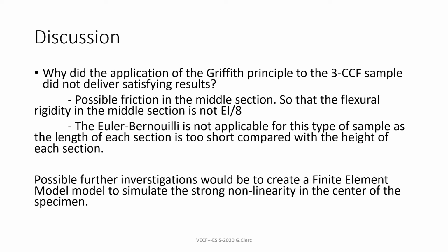For the ENF sample, we use flexural rigidity divided by 8 for the cracked region. But I'm not sure that's the case for the CCF sample, as there is probably a lot of friction due to the load which is applied in this central region and so on. So maybe another value than 8, something between 1 and 8, should be chosen, but which number? And probably that's something which is also not linear. It probably varies over the cracked region.